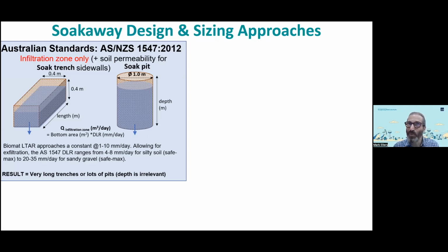Which leads us to the importance of the soakaway. Both of these case studies actually result from failures in soakaway designs, leading to other mitigation options. And so getting the design of the soakaway right is probably the most important part of septic tank design, because if you get that wrong, it surcharges into the septic tank and fills the septic tank prematurely.